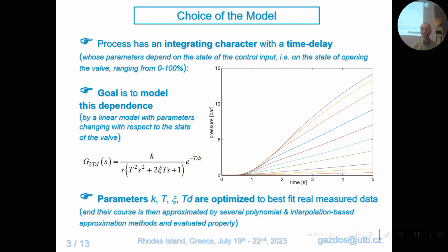When we analyzed these responses, we did some approximations. We found that these simple curves can be in a good way approximated by this transfer function. I guess you are familiar with control engineering terms like transfer function. So these curves can be approximated as an integrating system with some gain, with some time delay.